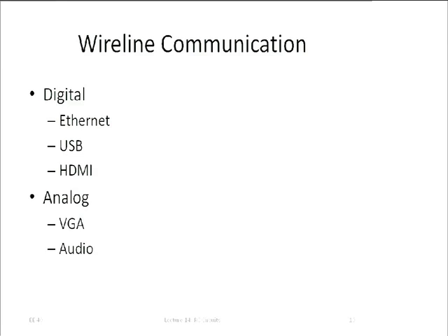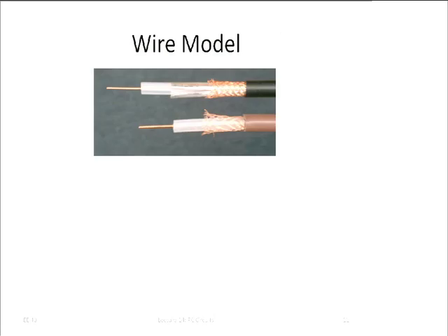So first of all, here is a picture of some cables, these sort of thicker coax cables. The way they are usually made is that there is an inner wire, copper typically, and then around it is some kind of insulating material, this whitish stuff. And then there is another conductor, this braided stuff there, also copper. And finally, there is a final insulating jacket. Well, if you look at this from a circuit designer point of view, what kind of elements could you use to model this? What does this look like?